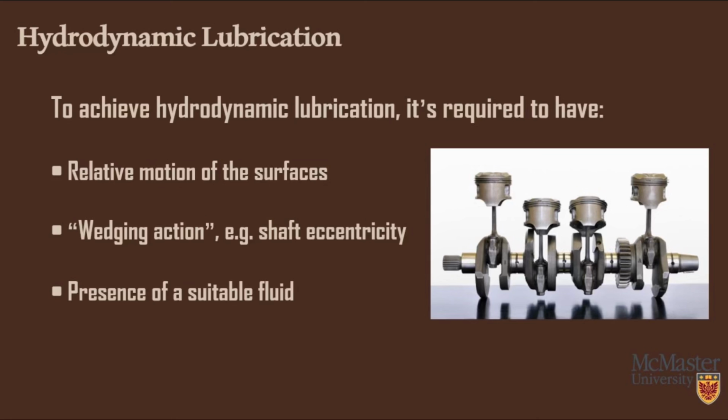Peak combustion load has instantaneous duration, and inertia and the transient squeeze film effect prevent the oil film from being squeezed out. That's all for today's introduction, and thank you for watching.